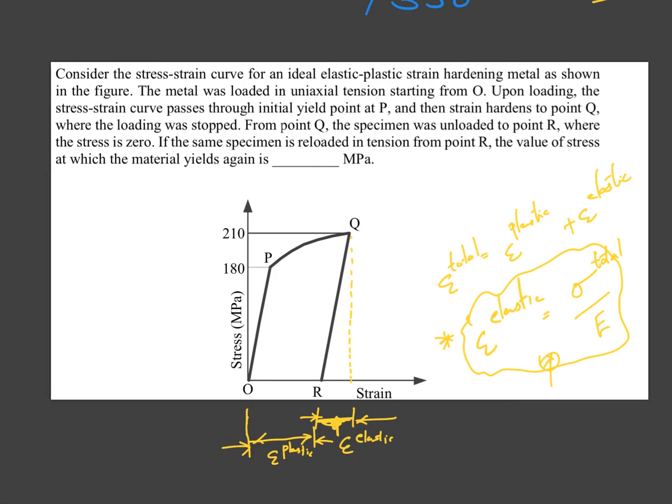Why is it so? It is so because when you subject a material to yielding, dislocations will be created. As you know, dislocations are the reason why our actual yield strengths are very less compared to the theoretical yield strengths.